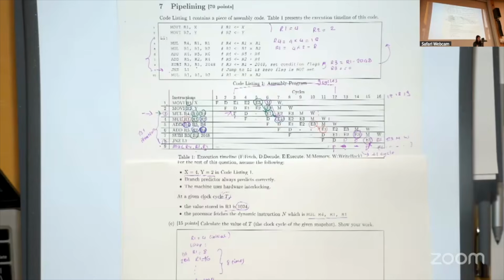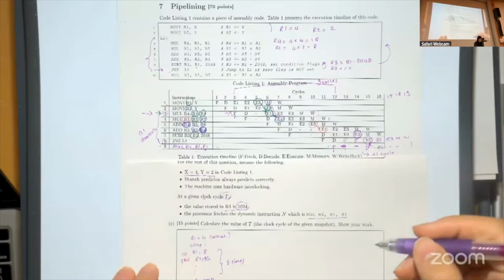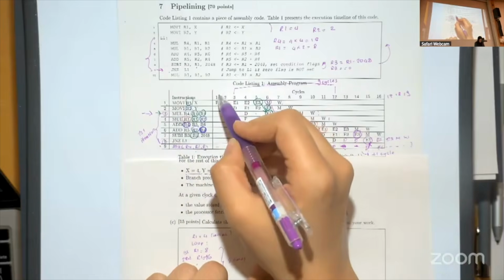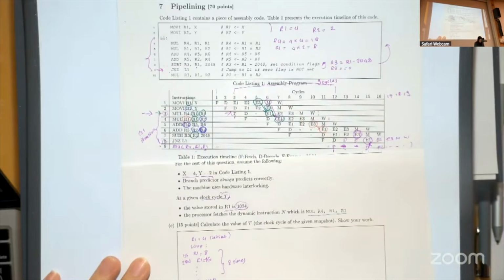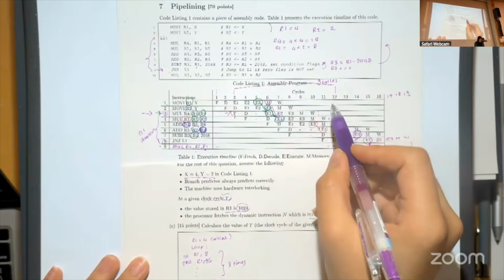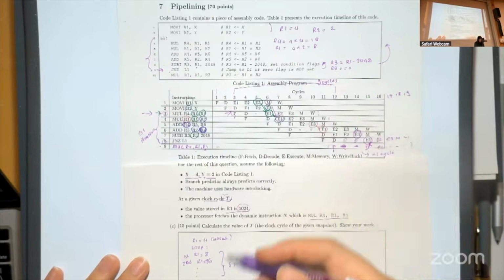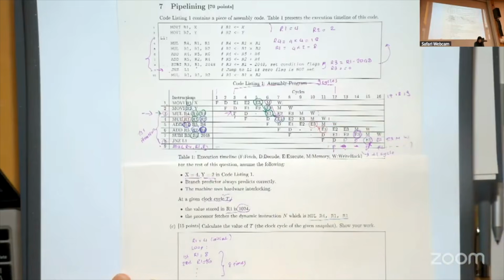I see some nods. Okay, so this means that first we have 2 cycles coming from initialization, and then the next loop iteration, which is the first loop iteration, will take 9 cycles. And then, okay, did I do something wrong? Okay, so this is 3 actually, because we are calculating like this. And then the next iterations, which are 7 iterations, because we counted the first iteration here, will take 10 cycles. And after this point, you get this number.